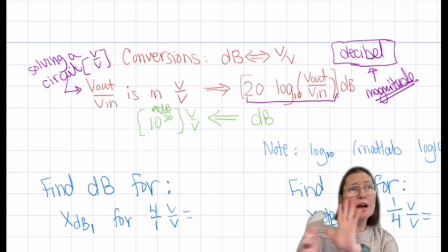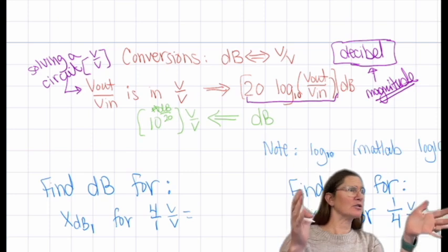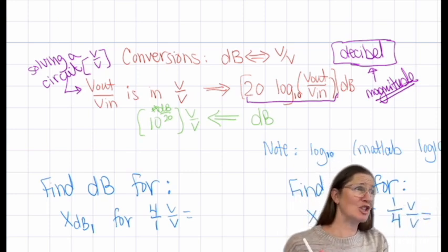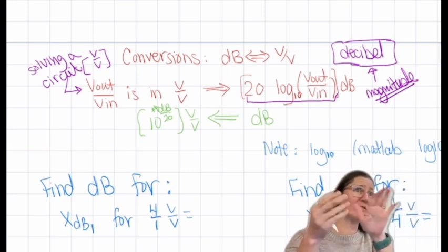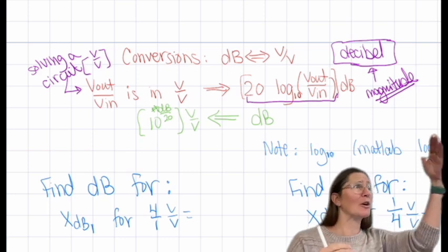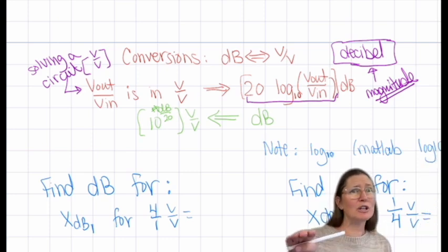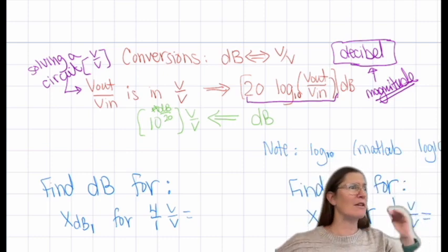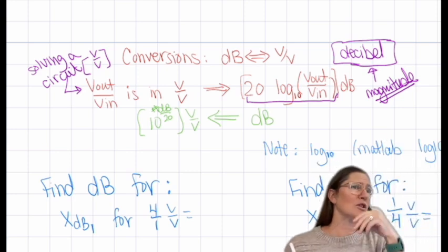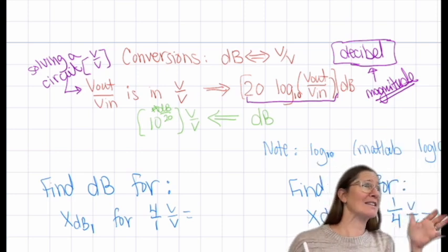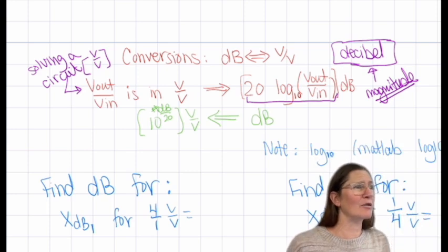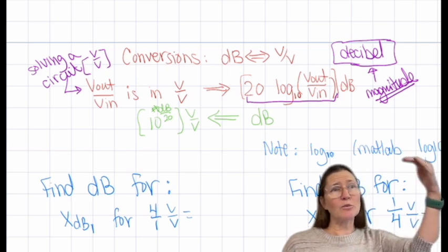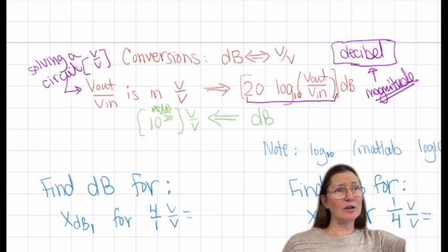To convert, say we have dB and we have some magnitude graph that we're given. If you want to, on an op amp data sheet, you can actually go look, and in the back of it there'll be this Bode plot, and you can see there's dB on one side and voltage, and it will show you a range, and then it will cut off after that frequency. So you can look at that now and understand this is in dB and this is over different frequencies.